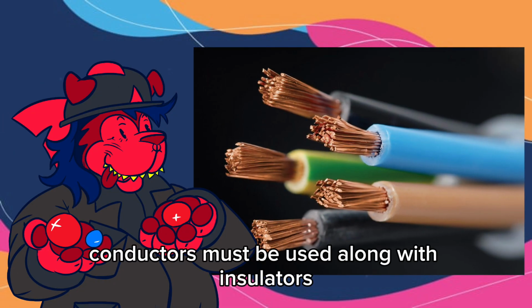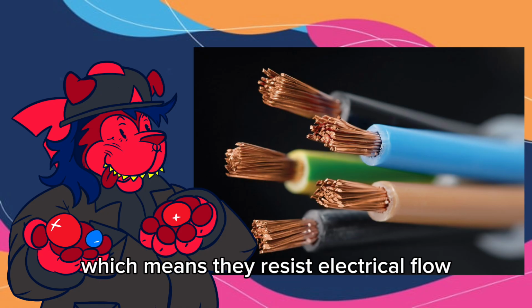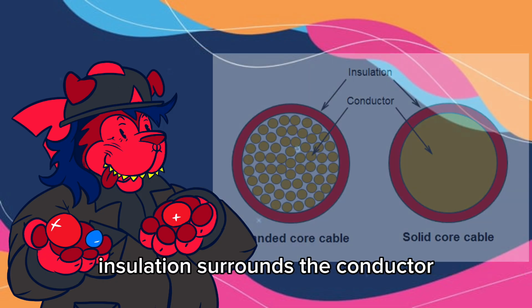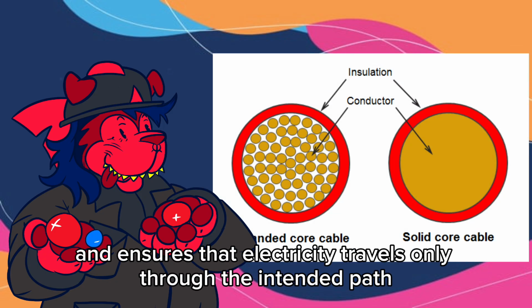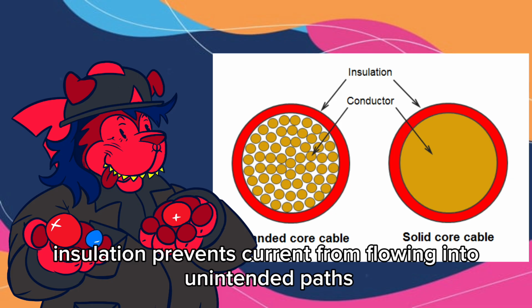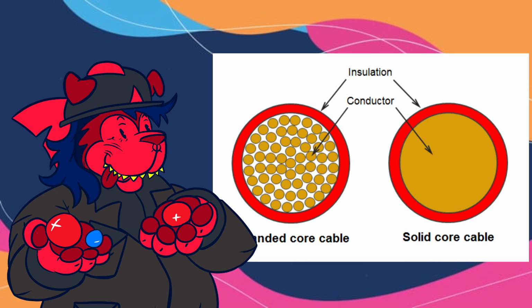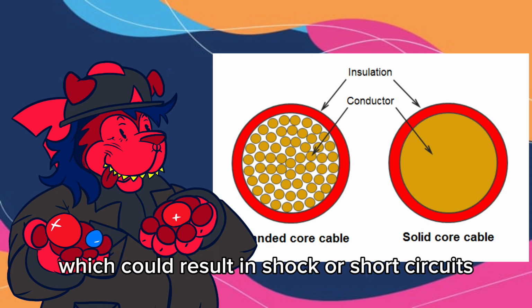Conductors must be used along with insulators. Insulators are materials with very few free electrons, which means they resist electrical flow. Insulation surrounds the conductor and ensures that electricity travels only through the intended path. Since electricity follows the path of least resistance, insulation prevents current from flowing into unintended paths, such as through a person or between conductors, which could result in shock or short circuits.